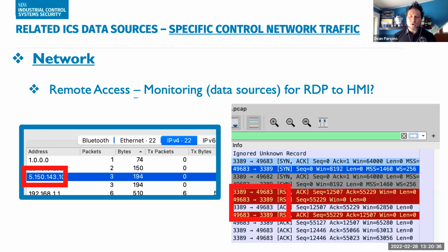On the screen, we do see network activity. This here is at the packet level, so we do have full packet capture. And then we do have evidence of C2, command and control activity, from the internal control network to the outbound internet, possibly, in this case here, for exfiltration, but we also see activity going directly to the HMI. Now, this is going to be interesting, and we'll come back to this when we start building hypotheses, because this is not something that's new. So gravitating towards the HMI, doing exfiltration, even pings, for example, as you see on screen with very low bit count, transmission count, et cetera, of packets and data can be beaconing to establish that C2.